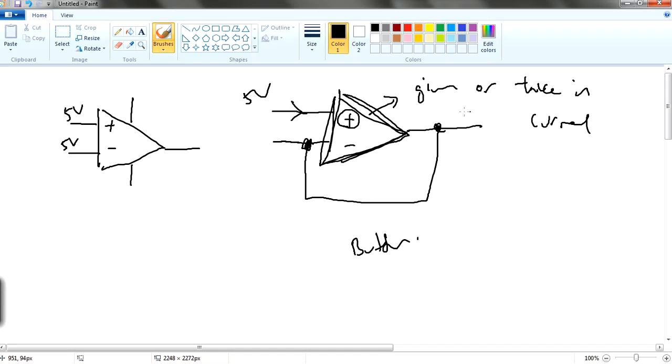However, this is the ideal case. For a non-ideal case, it may take in certain current. But in this case, for example, if this is the voltage in, the current actually flows if there's another thing connected here. The current will flow in this direction, into here, and then it goes out. It will not flow into this op amp. It will just flow in this direction.